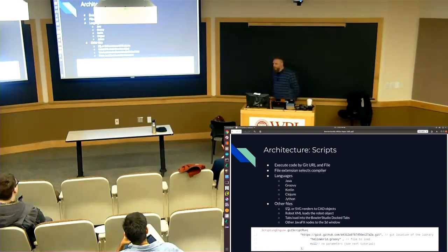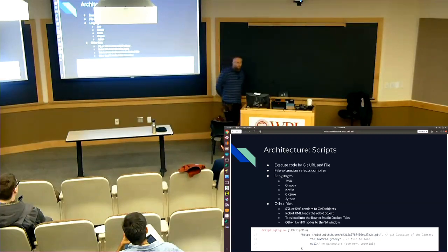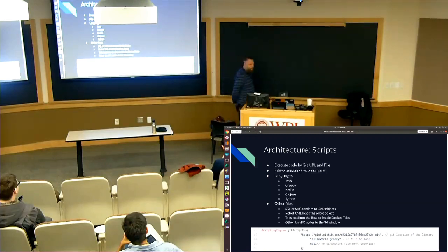Other file formats is the robot XML. It's a generic XML, but unlike a normal XML, you run it, and what it does is, as a standard static config file for your robot, it includes information about the robot, but also where to find the extra executing files for the robot and loads those as well and executes them. So running does perform an execution of sorts, or at least it kicks off an execution.